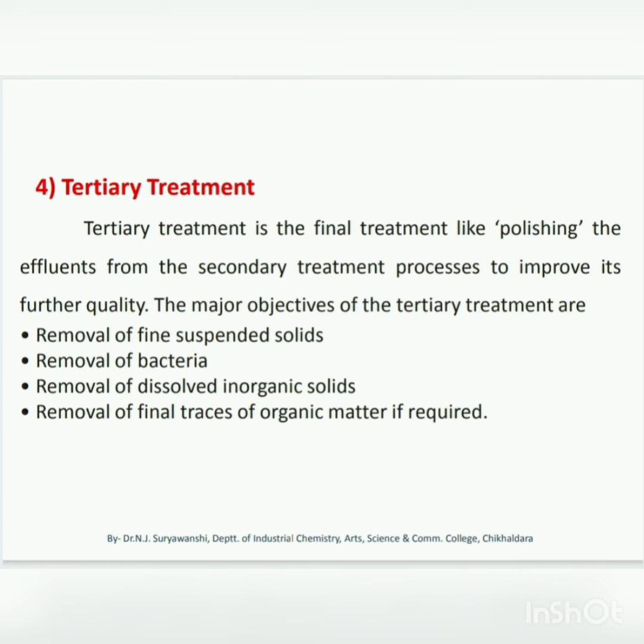Removal of finely divided suspended solids can be achieved with the help of microstrainers and sand filters. Removal of bacteria is carried out by retaining the effluents from secondary biological treatments in maturation ponds for a specified period of time. The final effluent is chlorinated if necessary. Removal of dissolved inorganic solids is a major problem with wastewaters from industries such as fertilizers, textile processing, tanning and electroplating. Any one of the following treatments can be employed.